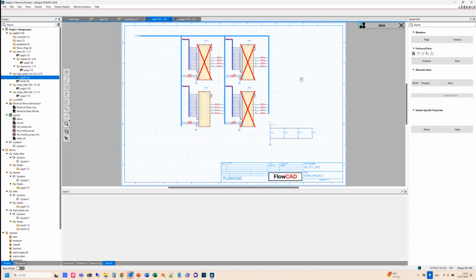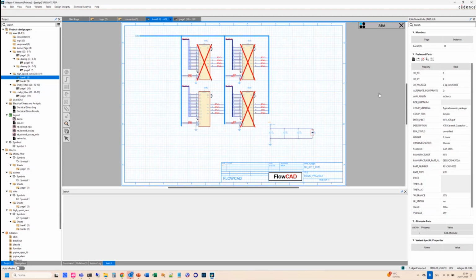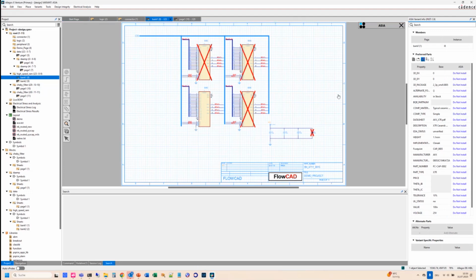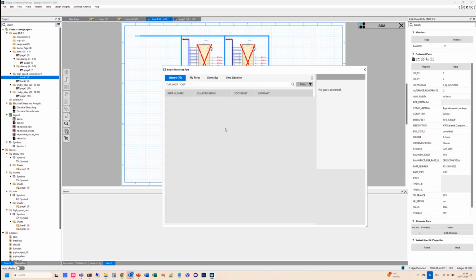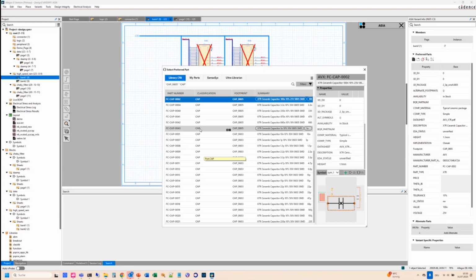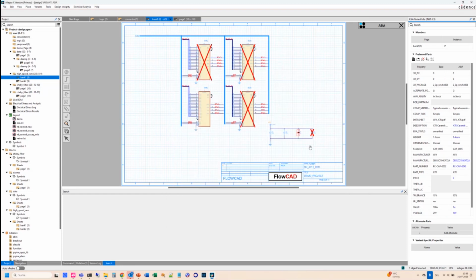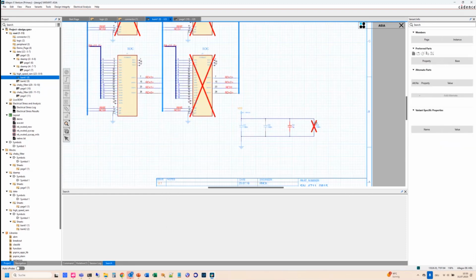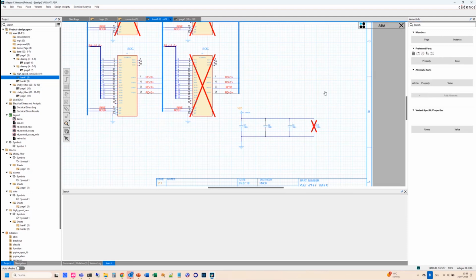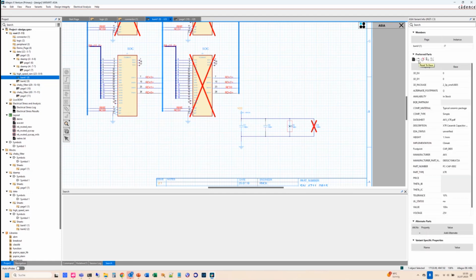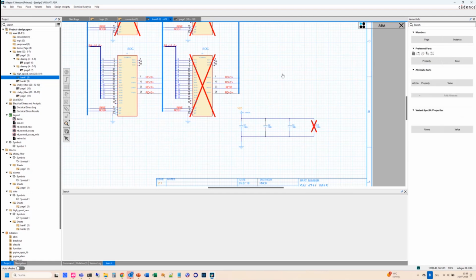And if you want to change something, as mentioned, this is really easy, straightforward. Simply click inside of the schematic on a part and say do not install. Or simply click on a part and use a different cap for that. So it's shortly browsing through this component list, and simply use a different one. You see here it's crossed out, or even in a different color, so you see that it's a different value in this case. And if you want to get rid of this, simply use revert or reset to base. So as mentioned, pretty easy to use.